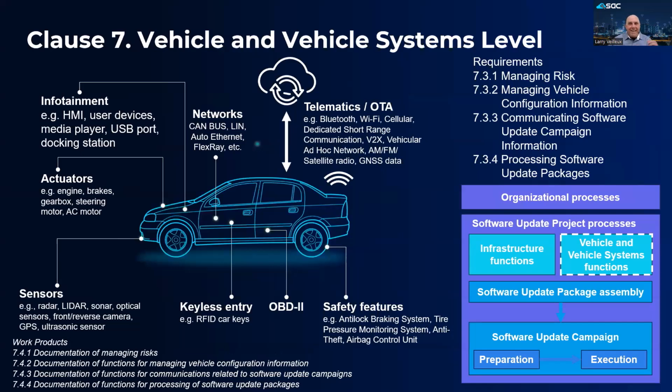Busy slide, I know. I just wanted you to be thinking about all the different vehicle entry points that can be leveraged by the infrastructure to actually execute the software update. The entry point can be physical, requiring direct access to the vehicle, such as a repair technician connecting to the OBD2 ports, or it could be over the air, or OTA, with updates being pushed from the OEM backend or cloud to the vehicle from some remote location.